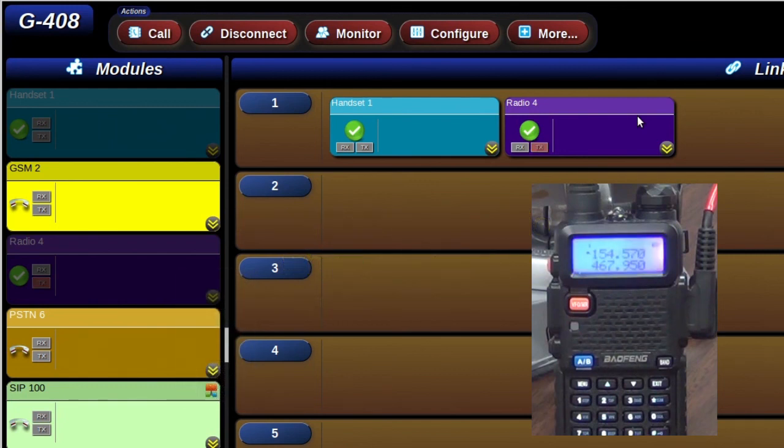So you see that? This time the system tried multiple times to get a channel before giving up. You heard those S tones, or S codes, in the audio. And after 6 seconds, the system just played out the audio that it had buffered up. It never thinks it got a channel, so it just treated the transmit delay like it was a normal transmit delay, and played out the audio.